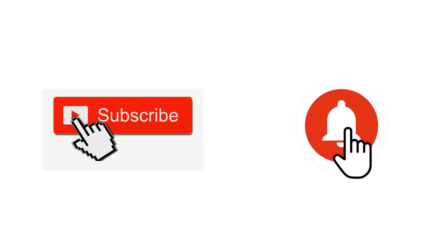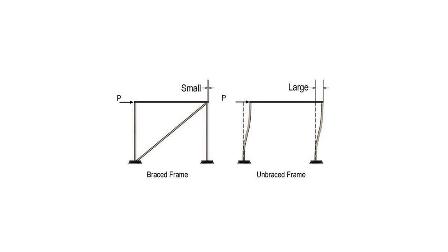Okay, so at the very first, assuming you are a beginner, the basic function of a bracing is to carry the lateral load. Let's say you have a frame with no bracing. In that case, if you have any lateral load, definitely the frame is stable if you have provided all these connections as moment connections. The problem is that the deflection is much larger.